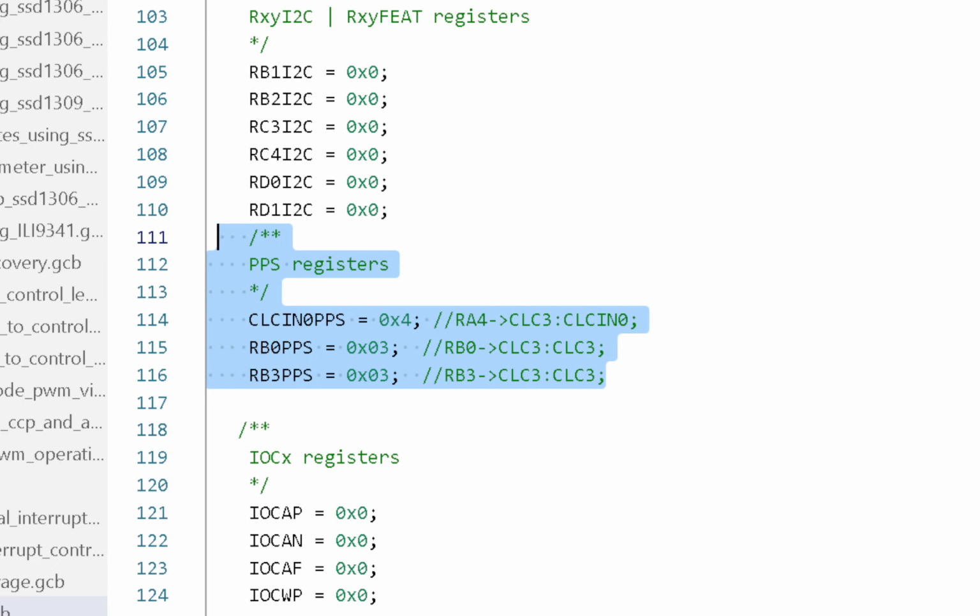You can do that in PPS tool, but you'll be there for about an hour doing it, okay? And you know it's going to work because we've taken it directly from Microchip's tool. So what we've got is the PPS section lifted directly from Microchip's tool, and we've got the CLC section lifted directly from the tool. The rest of this program says, here is my chip, here's all my constants, and there is no program. Look, no code, no interrupt, just CLC magic. That's what I've written.